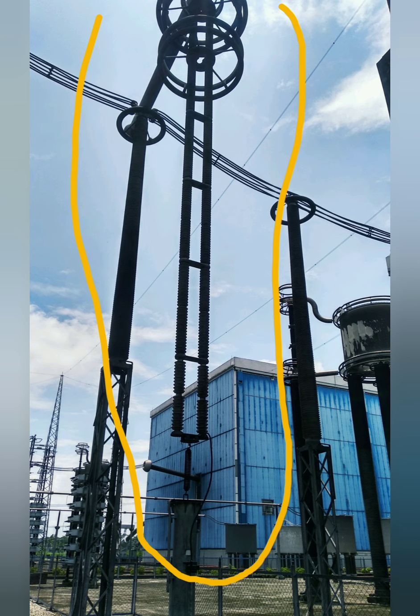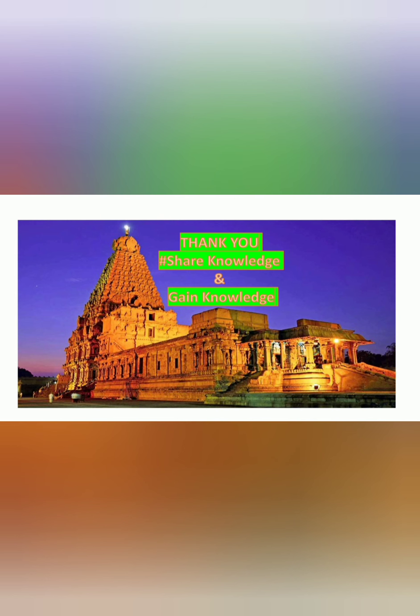Then all the stacks will be connected in series, and then one line, which means one cable, will be connected with your indicating or monitoring system, which means the surge monitors. Further, with the connection of the surge monitor there will be some earthing provided, and by the earthing the leakage current will flow to the ground. Hope you understand the basics of surge arresters, lightning arresters or surge absorbers.